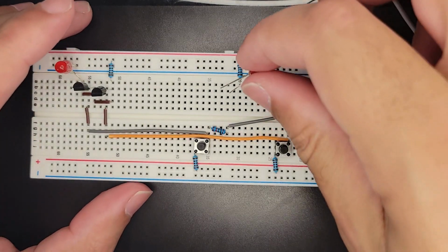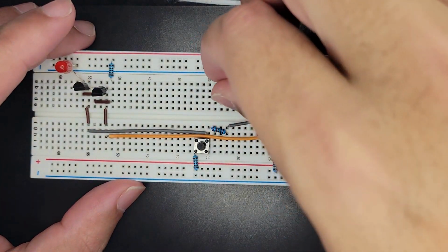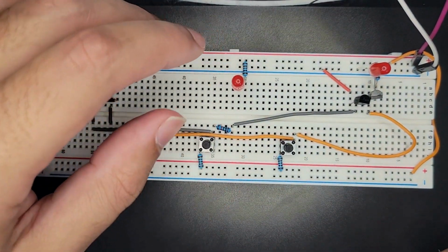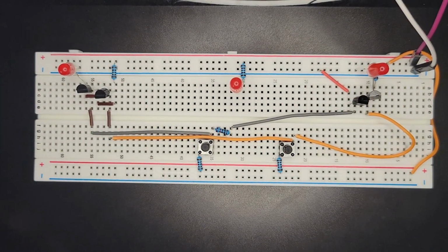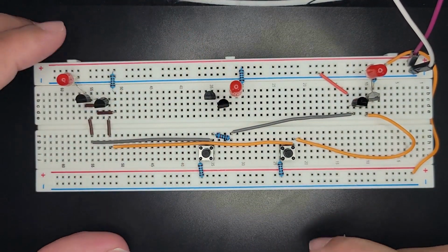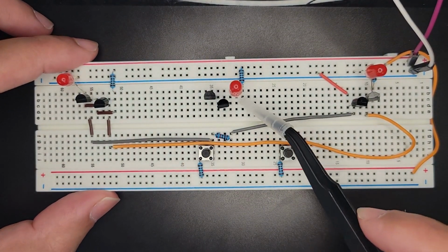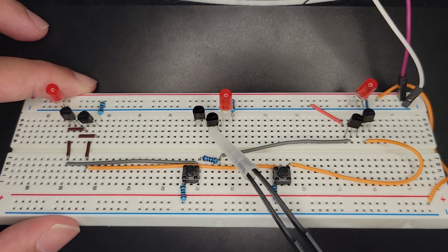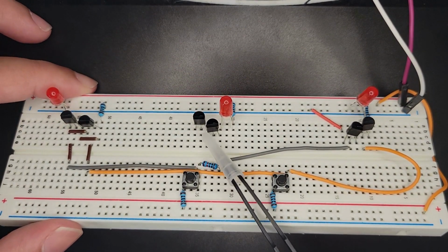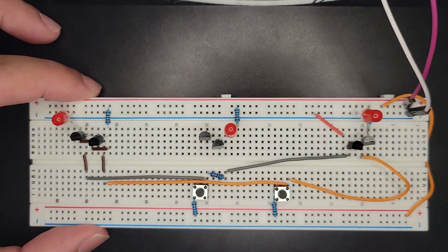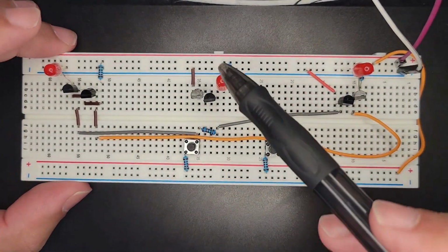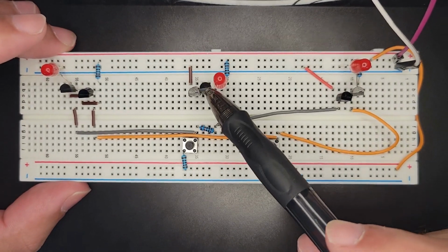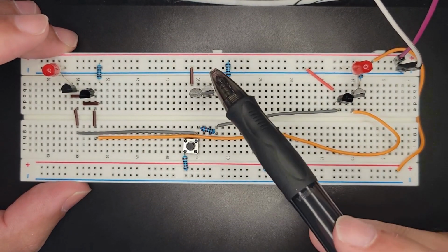So we are going to have an LED, which gets our resistor. Our resistor goes into LED, and then it goes into two transistors in series. All right. So we have our LED going into transistor A's collector, which goes into transistor B's collector, and then needs to go to ground. So by default, this guy's getting energy, but he can't go home. When we activate both these transistors, it should go home.